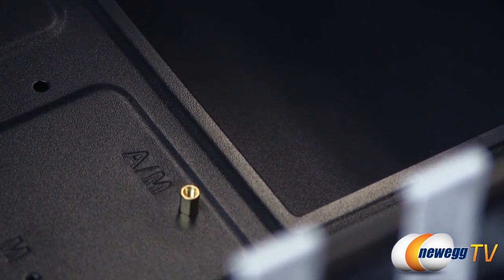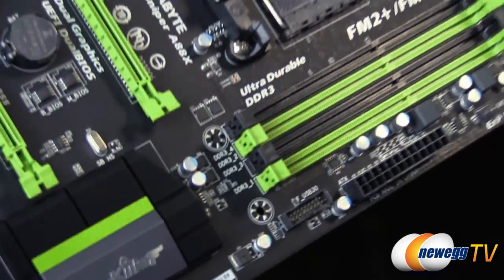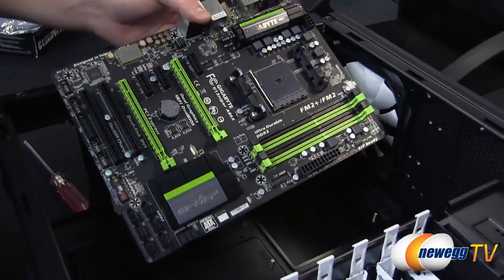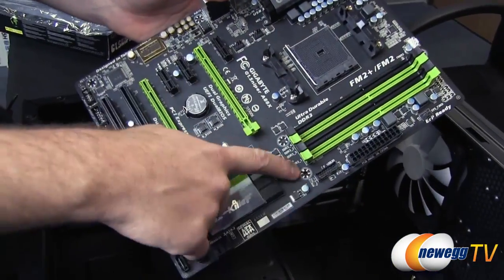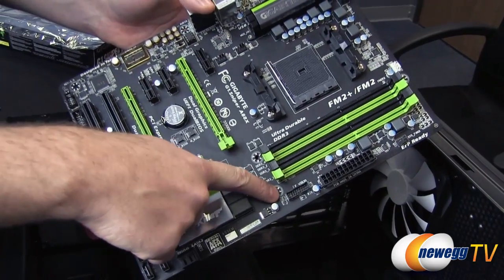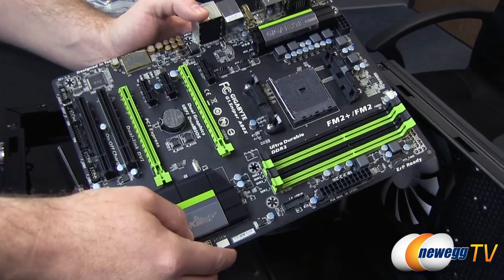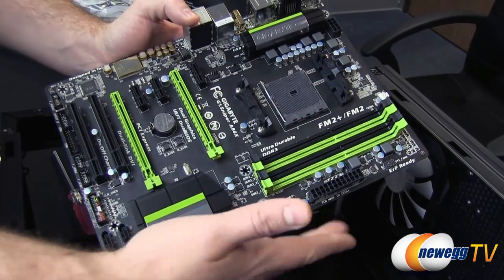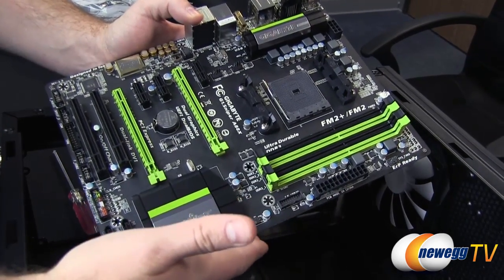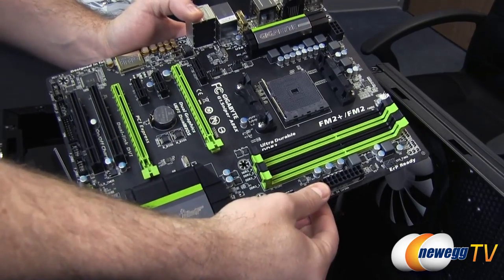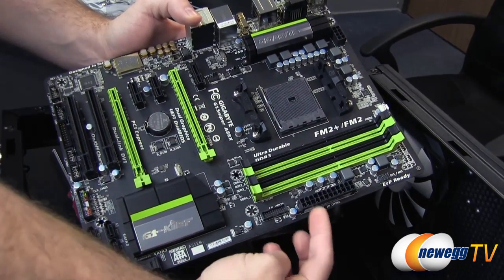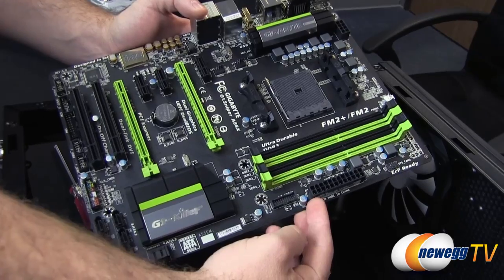But back to our dilemma and the main non-standard thing when it comes to this particular video, and that is how do we deal with this last standoff point? We have it there on the motherboard, but not on the case. There's a couple things we could do. I would be okay just not having a standoff there, but bear in mind this side of the board is going to be kind of suspended, and you might want to be careful about putting pressure, for example, when you actually plug in your main 24-pin power connector.